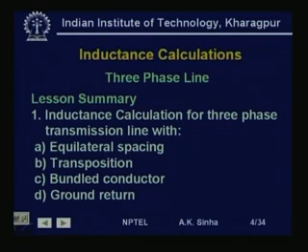Now, we will start our lesson 4, which will be on inductance calculations for 3-phase transmission lines. In this lesson we will discuss inductance calculation for 3-phase transmission lines with equilateral spacing, then with transposition, again when we are using bundle conductor lines, and finally lines with ground return.